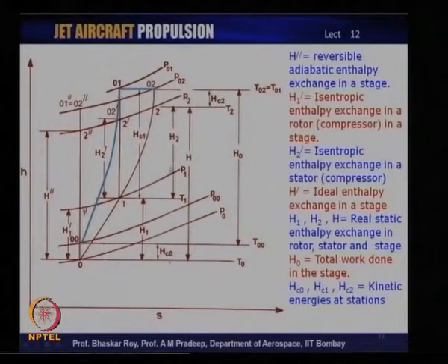As you can see here, this is the ideal work that is being done, the ideal adiabatic work in a stage, and then you have the work split up in rotor and stator, and then of course, you have the real work done over here in H, that is the real work done through the stage.